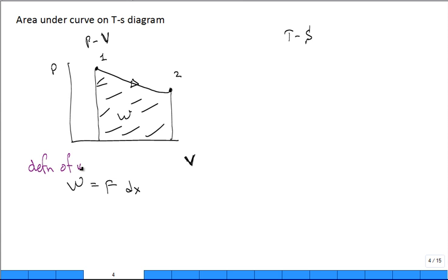Definition of work. Maybe that's not a definition, but it is. It's from mechanical work. Understanding what is exactly mechanical work, right? If I put an area here and an area there, did I change the work? No, but I can group that X dA or A dX, and that's a dV. What's force per unit area? Pressure. So work, integral F dX or integral P dV.